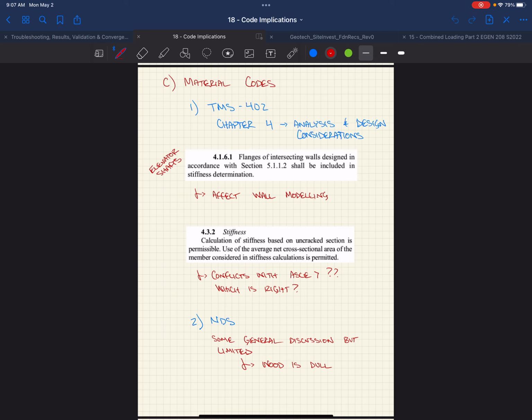So they've changed the detailing requirements in order to get that, where this is 2t, 2 times the thickness of the plate, and all this other weird stuff. So you've got this going on, right? Well, our model is modeling this brace as centerline to centerline of the beam-column intersection, right? Well, when you go to design these braces, if you did this centerline to centerline, you're going to have an unbraced length that's quite a bit longer than the actual unbraced length of our brace, right?